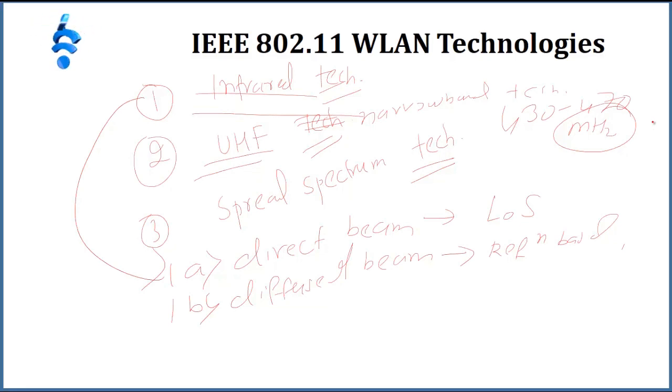Many modern UHF systems are actually synthesized radio technology. This refers to the way UHF channels otherwise required factory installation of a unique crystal for each possible channel frequency. Modern UHF systems allow an access point to be individually configured for operation on one of several pre-programmed frequencies. Terminals are programmed with a list of frequencies being used in installed APs, allowing them to change frequencies when roaming. To increase the throughput, which was the last point of our limitations, access points may be installed with overlapping coverage but use different frequencies.